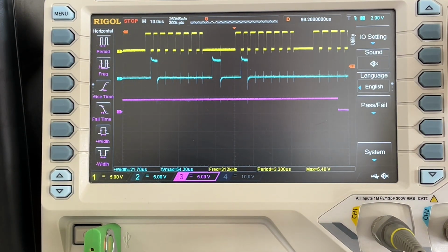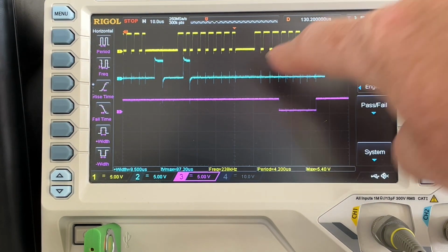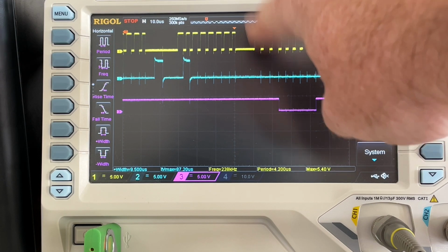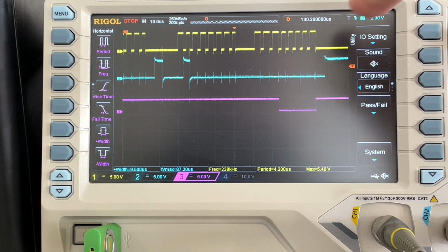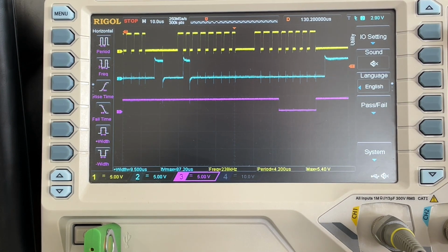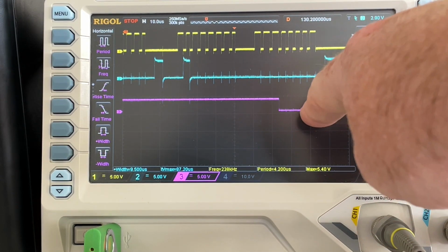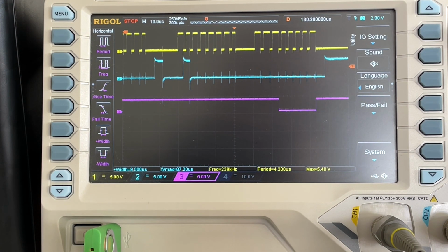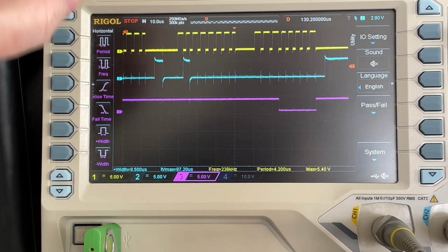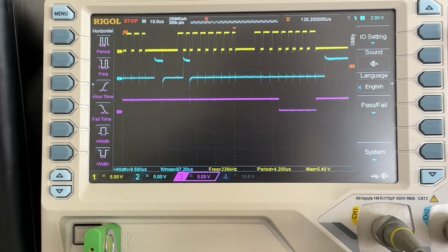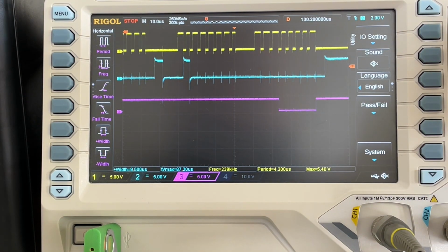As you can see, what happens then is that we keep the signal low. The data out from the computer signal stays low, but we still keep clocking. We send a bunch of clock signals, and that's clocking the data back from the video board. The video board sees the clock signals, and it uses them to coordinate sending back the data. So we've done the read. We said set up this register, that was 2 bytes, and then read it. That was 1 byte for the read command, and 1 byte coming back in the opposite direction is the data coming back from the video board.